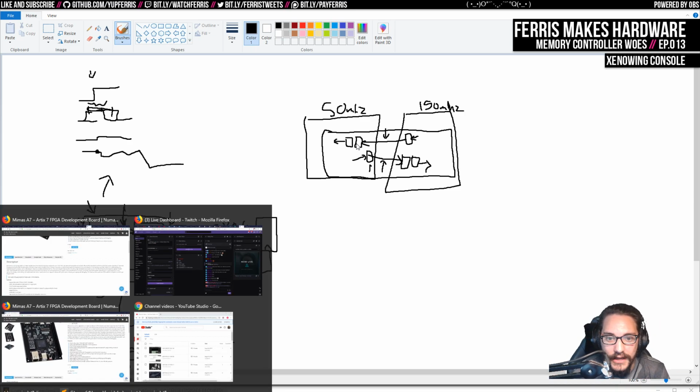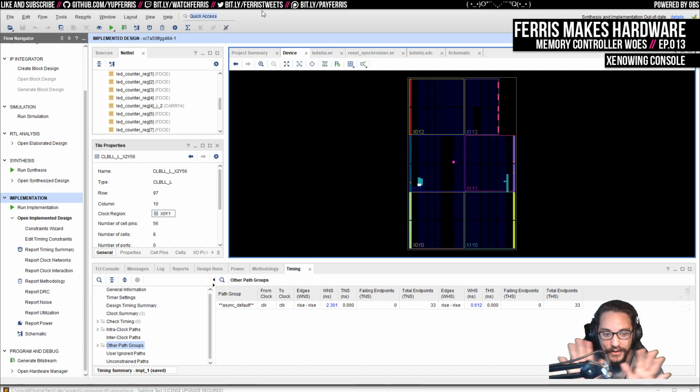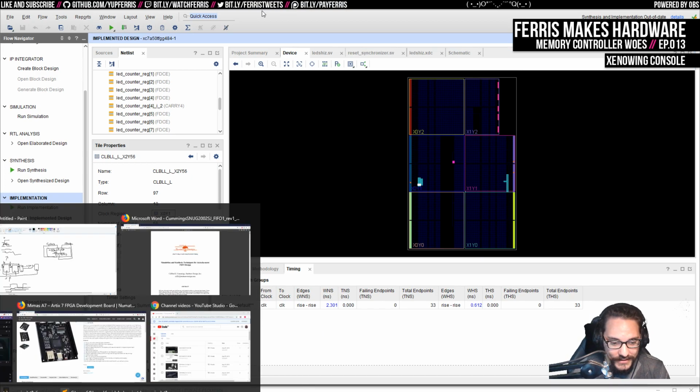And also generally, a lot of these IP generators for a lot of these FPGA tools will of course have FIFO designs that you can just grab. So I need a FIFO of 32 elements, and they need to be this many bits wide, and they're going to be on separate clocks on the inputs, and then it's easy to hook up. And that will also have the right constraints for all the timing analysis and everything, sort of built in and done for you, which is really nice. So if you're used to multi-threaded programming with FIFOs, then this is obviously not really a new idea. So that's a good way to cross these clocks.